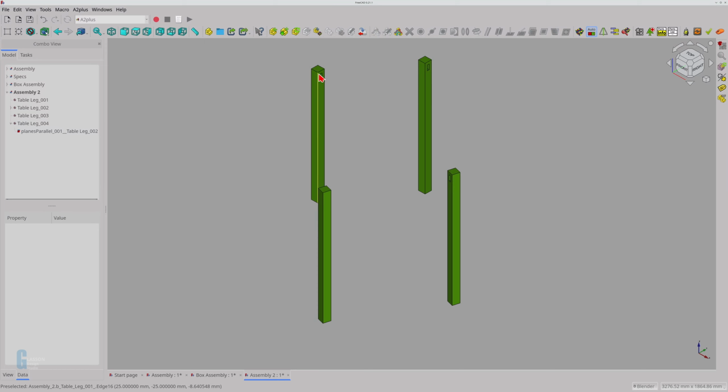I don't use this feature because the degrees of freedom labels don't show it as being fixed until a constraint is applied to the part. I discovered that you can have multiple fixed parts in your assembly. I haven't needed to fix one part, let alone multiple, so I don't really see the benefit of doing so. Please leave a comment below if you can think of a reason.